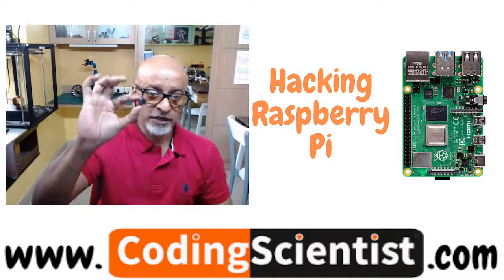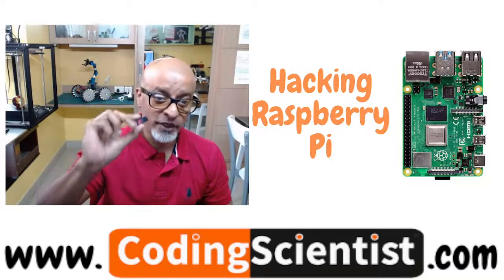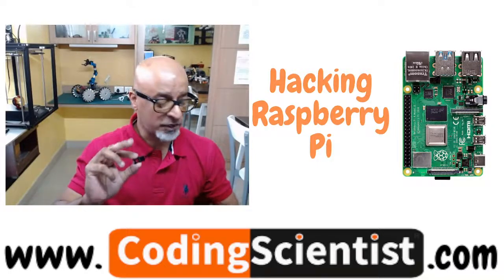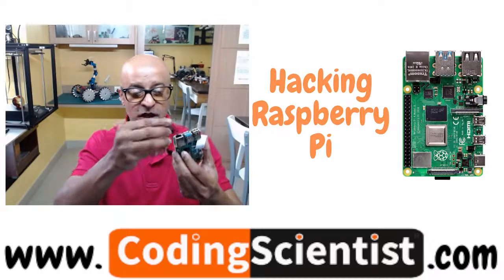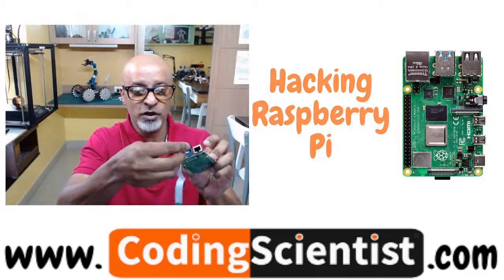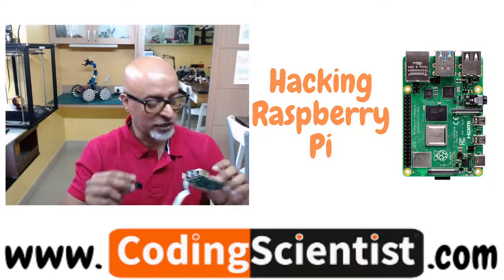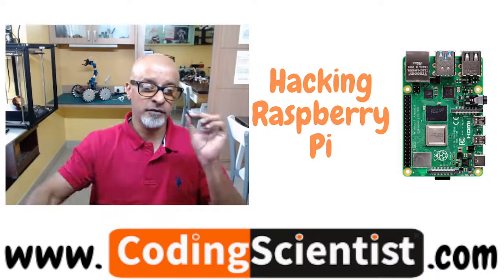Once you insert this SD card, it has to go into your Windows machine, not the Raspberry Pi. Do not put this into your Raspberry Pi. I have seen people getting confused and putting the SD card writer in one of the USB ports here. No, that's wrong. So go ahead and plug this into your Windows machine.